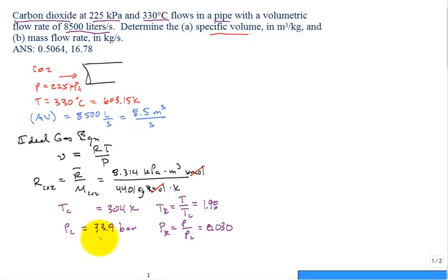And then the T sub R was close to 2. There's a line, T sub R close to 2. It's tucked up here. The compressibility factor Z is about 1. You would treat it as an ideal gas. We have justified treating this CO2 at this pressure and temperature as an ideal gas.